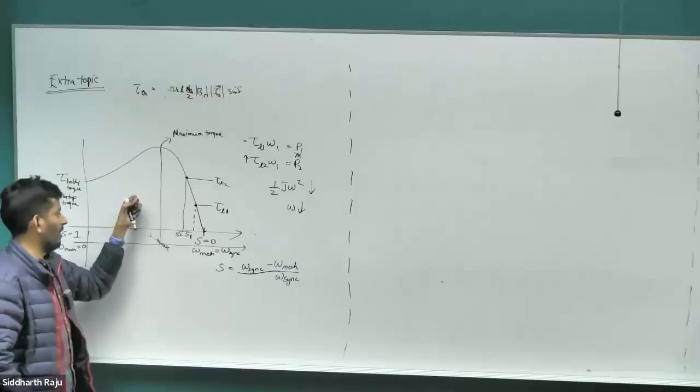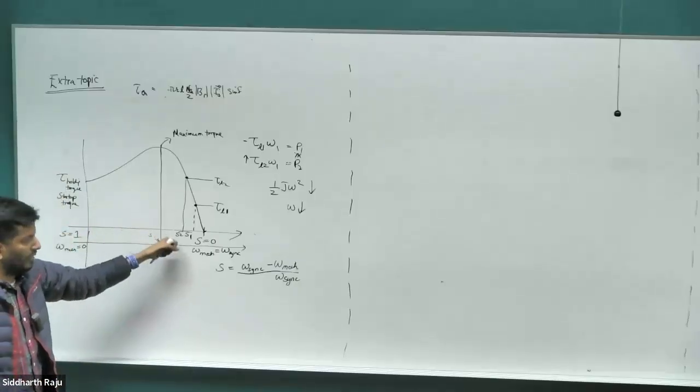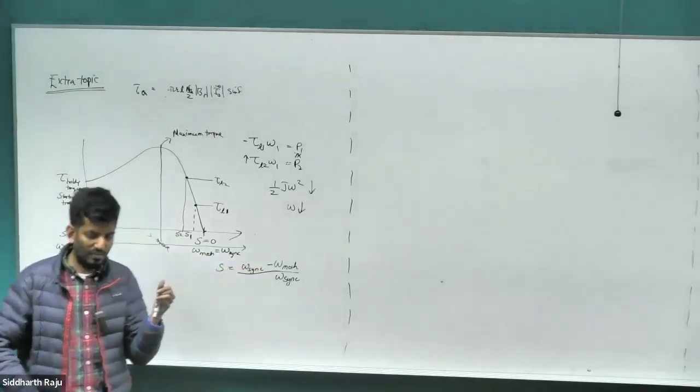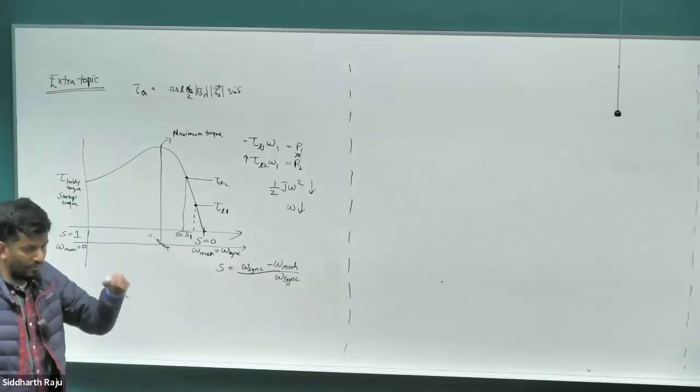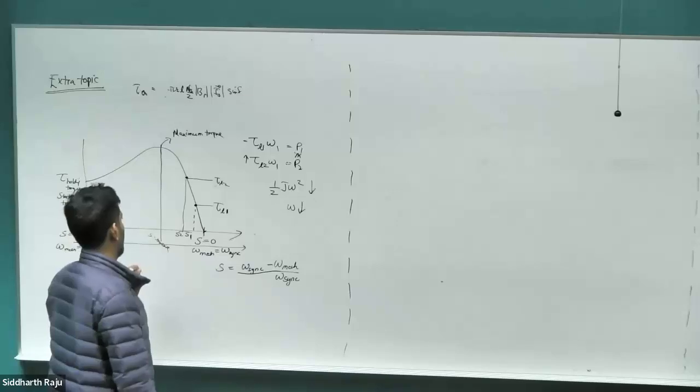Right? But in the case of an induction motor, the speed itself was a constant in that case. In the case of an induction motor, the speed is not a constant. As the slip changes, the mechanical speed itself starts to change. So it always starts to keep falling behind and behind. The rotor keeps slowing further and further. It doesn't operate in a synchronous manner.